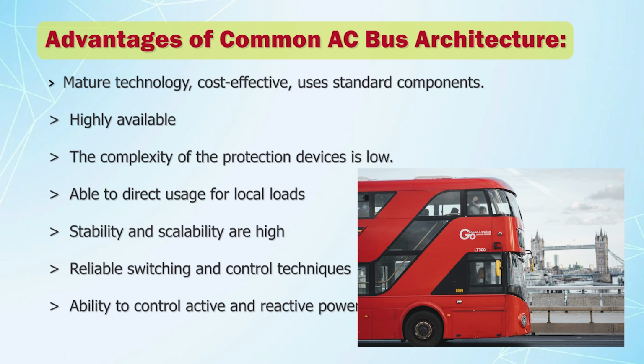This is the good thing whenever we put these converters in the charging station. We can also control active and reactive power by providing proper switching signals through our control to these devices, and for medium power levels, people are using IGBTs.